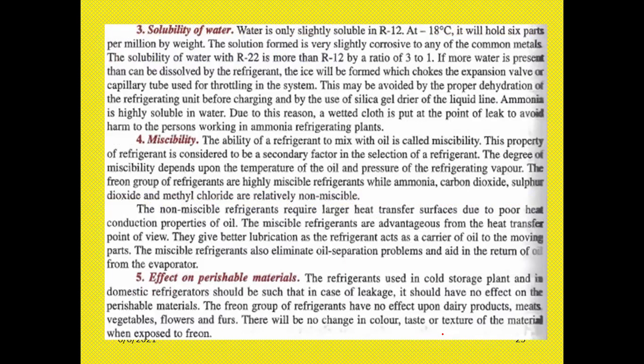Third one is the solubility of vapor. Next one: water is only slightly soluble in R12 at 18 degrees centigrade. It will hold 6 parts per million by weight.